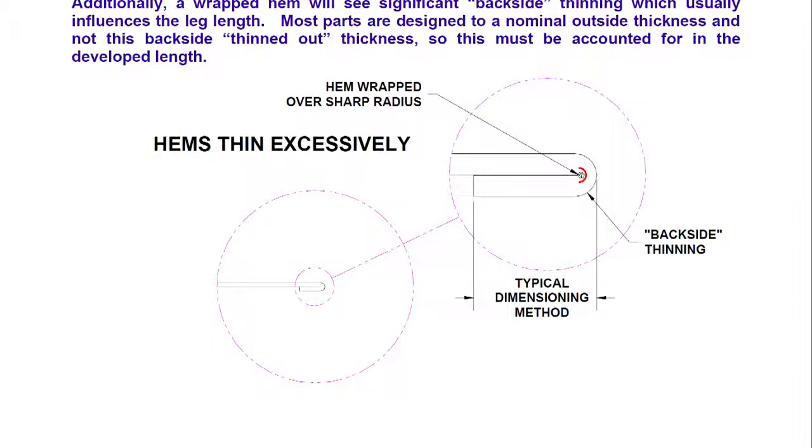At this point it will become obvious to you that if this is the rolling direction of the grain structure, it obviously bends easily. But if the rolling direction of the raw material was this, chances are it will break here. So, we are in trouble.